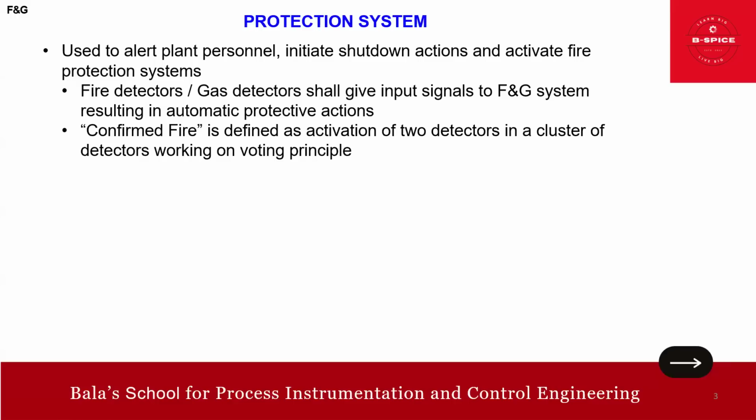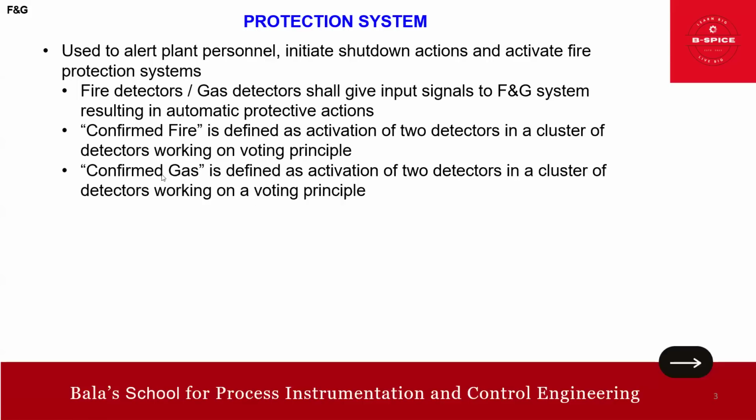There is some terminology I also want to talk about in the protection system. Confirmed fire means activation of two detectors in a cluster of detectors working on a voting principle. You got it, friends? Very important. Confirmed gas is defined as an activation of two detectors in a cluster of detectors working on the voting principle.